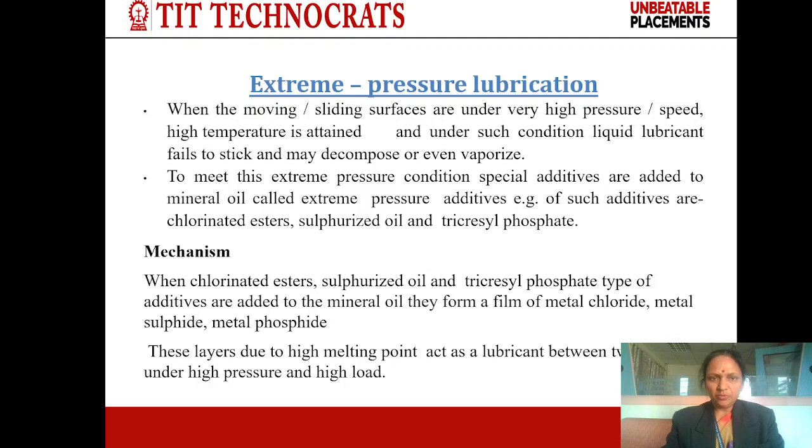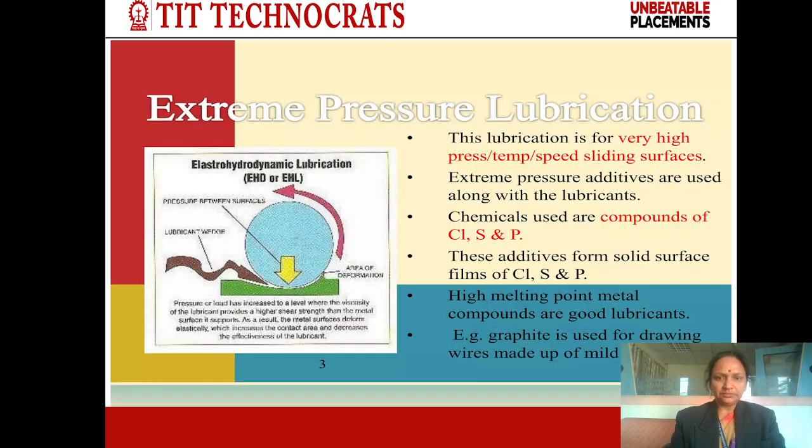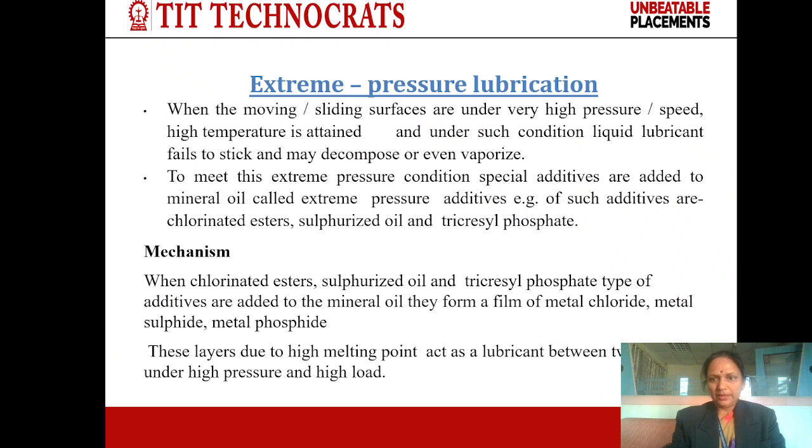The third type of lubrication is extreme pressure lubrication. When the moving or sliding surfaces are under very high pressure and speed, high temperature is attained, and under such conditions, liquid lubricants fail to stick and may decompose or even vaporize. To meet this extreme pressure condition, special additives are added to mineral oil, called extreme pressure additives. Examples of such additives are chlorinated ester, sulfurized oil, and tricresyl phosphate.